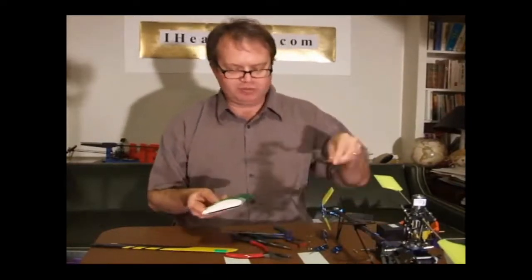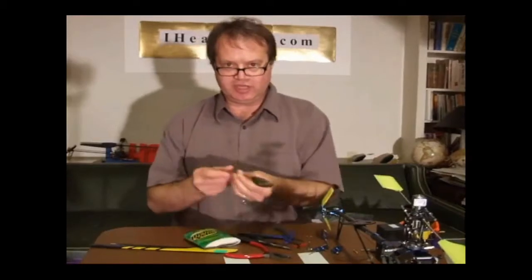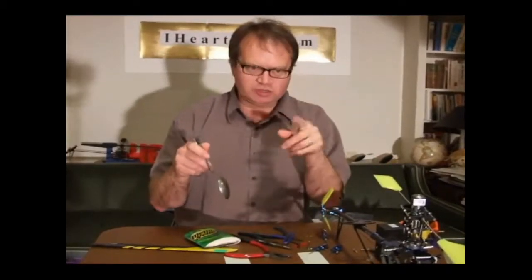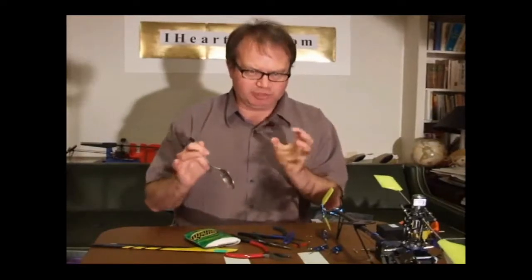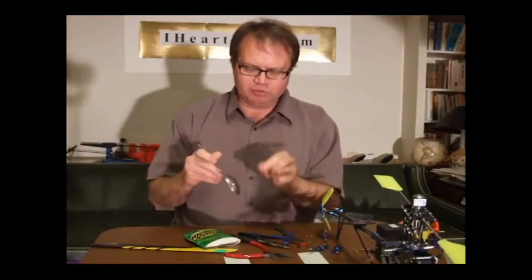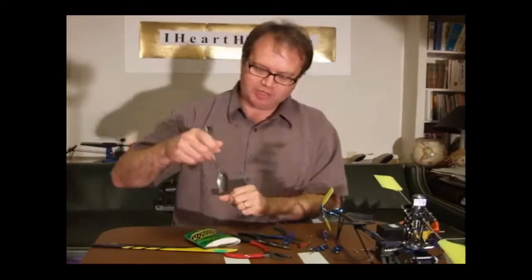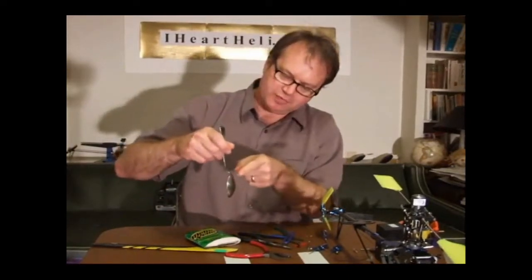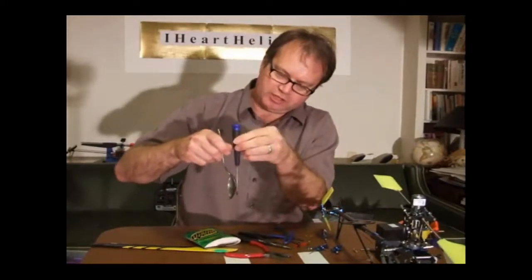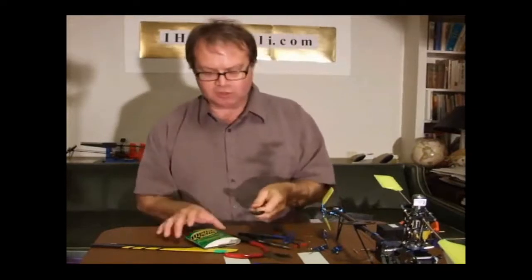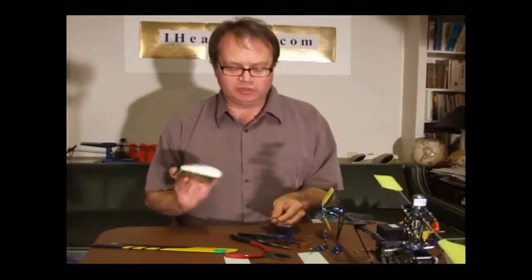Now, you can see that with a spoon. You can do that yourself. Take a spoon, take it over to the faucet and run some water. Don't run it so there's bubbles in it because that creates turbulence in the water, and we want a nice smooth laminar flow. So run the water with no bubbles in it, and then put the spoon up next to it. And you'll see the water will cling to the spoon. It will bend around the back of the spoon, and it will go this way. So that is really what's creating lift.